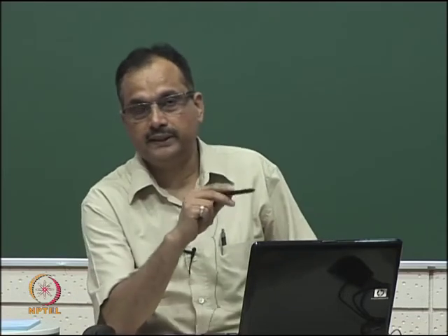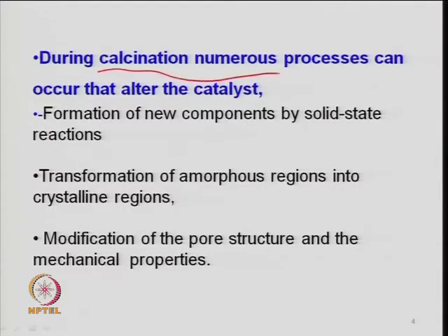As I said earlier, calcination or sintering becomes a crucial step, because when you have a nitrate salt, or chloride, it is converted to the oxide. In the presence of ambient air or oxygen, you heat the sample at a certain temperature, and maybe for a certain time. So temperature and time are very important, and this is what you call calcination, which we discussed last time.